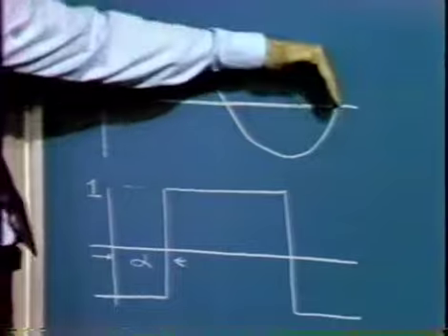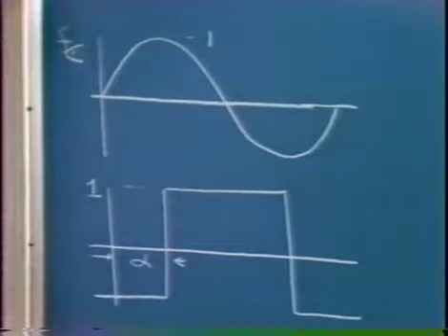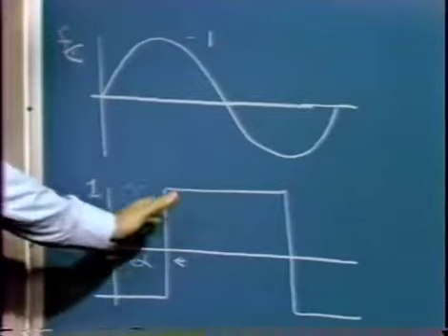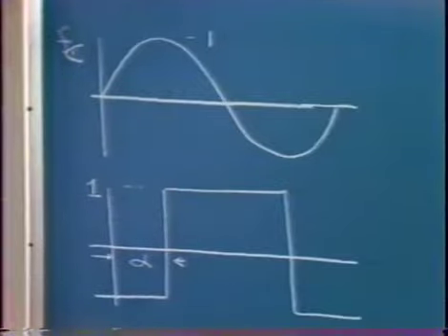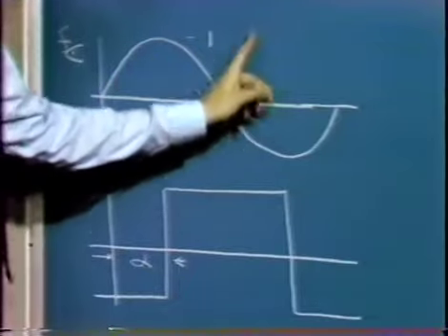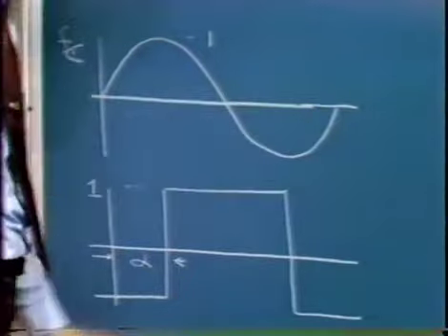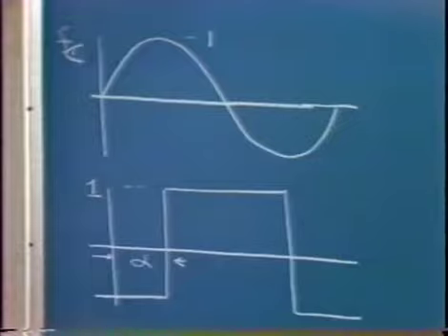So the output from the phase detector prior to filtering would be a full wave rectified sine wave. If we have 90 degrees of relative phase shift, we find out that the average value of the output is 0. We get little segments that are this segment and that kind of sinusoidal segment. When we average those, we get 0 for an output.